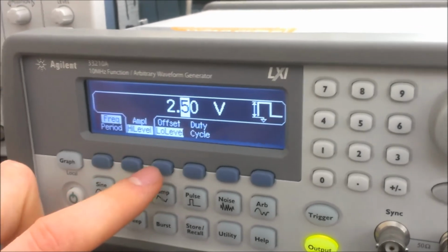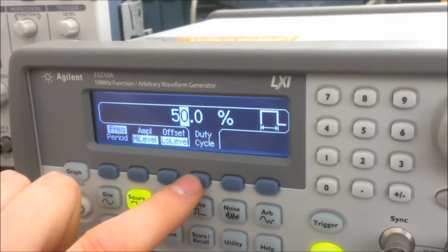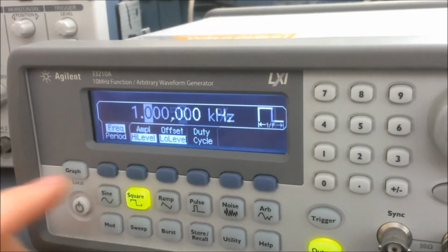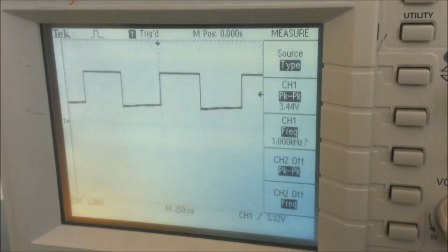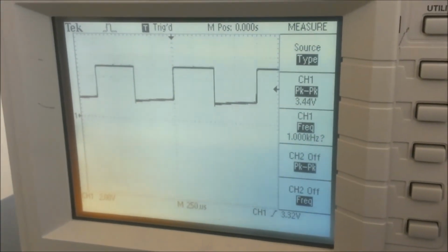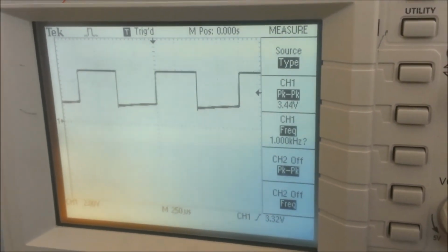We have roughly the same settings as we did on the high side gate driver with the high side switch. Now we're going to come to the oscilloscope. And this is again VDS, showing that the MOSFET is indeed switching, MOSFET 1.